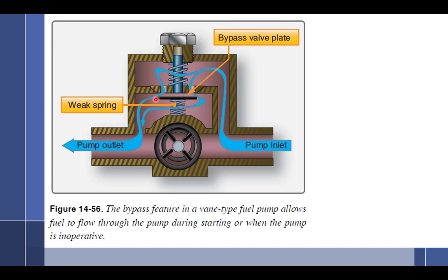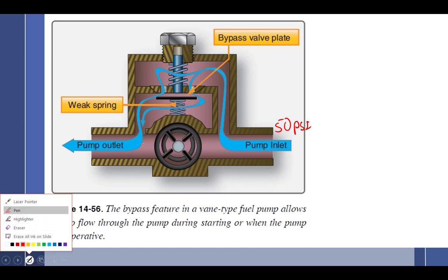When will this plate close? When the pressure of the pump inlet is weaker than that spring. Well said. When the pressure here from the engine-driven pump exceeds the boost pump, then it will close. Because what if the inlet pump pressure was, let's say, 50 psi coming in, and I'm barely turning this, so this is only 10 psi?